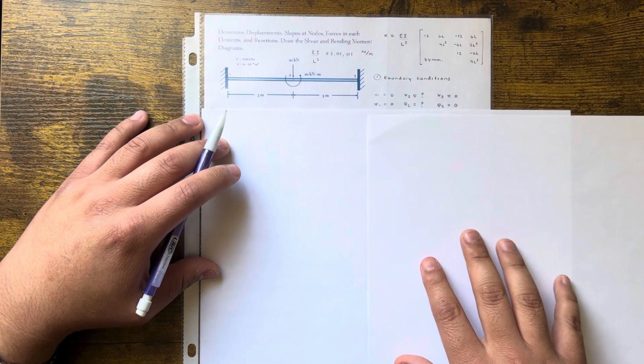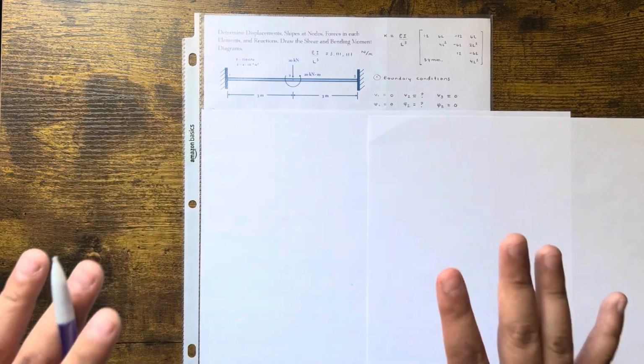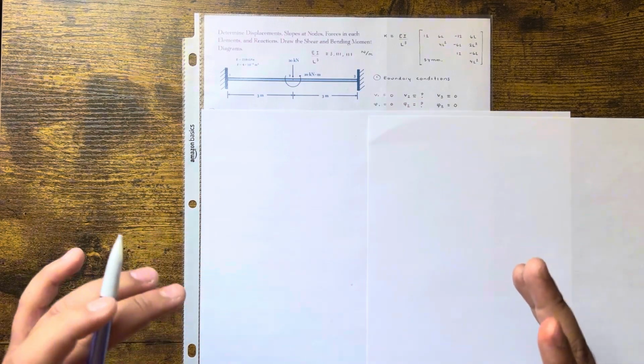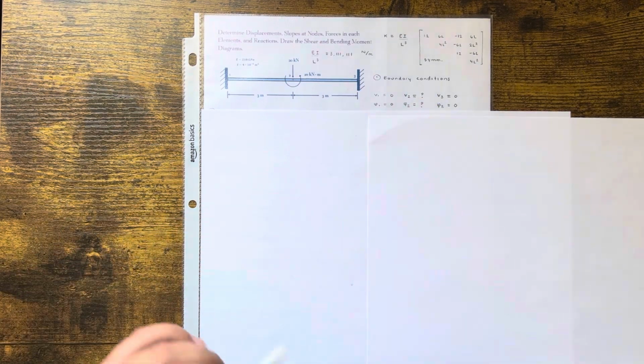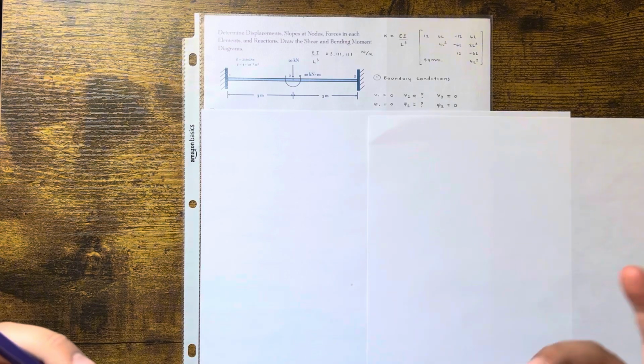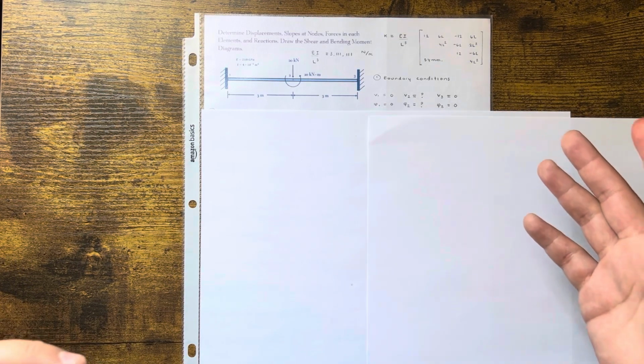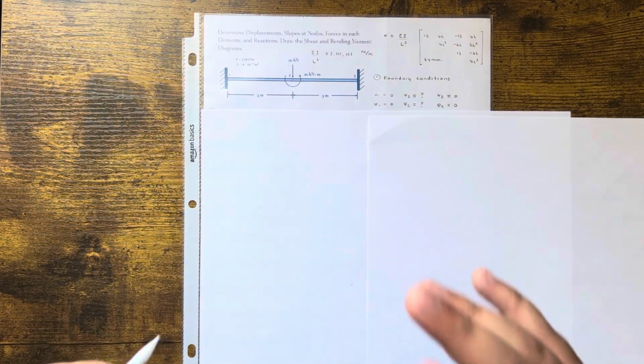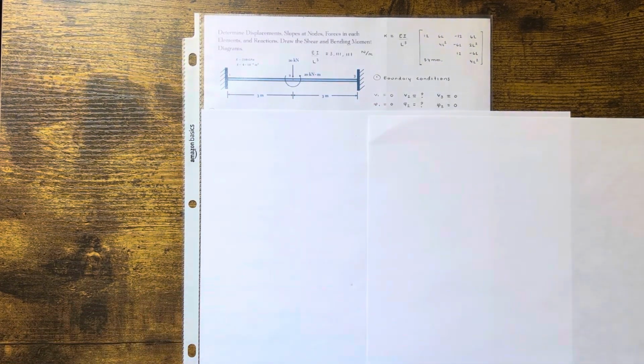So step number 1 on these problems, right? You start with your boundary conditions. So this is where the majority of FEA happens. You got to know this. This is either going to make or break you on the exam, right? You got to know how to set this up before you move on. If not, it's going to mess up your whole problem. And after that, it's just algebra. So this really is the biggest part of FEA, knowing how to identify the boundary conditions and then your external forces and moments in this case.